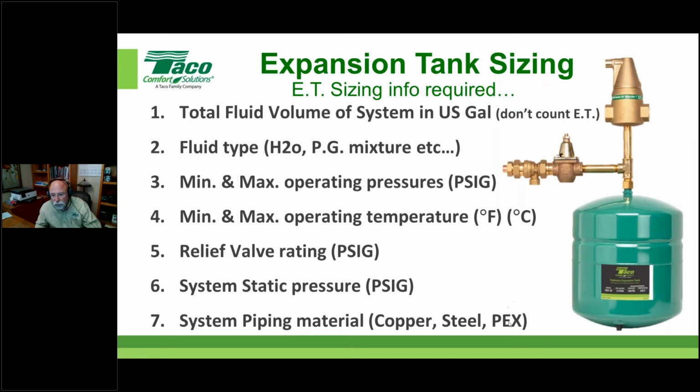I got one thrown in here, like Taco's, which if I have time, I'll show you at least an example of it. It's going to ask you whether your system is copper or steel, because the coefficients of expansion of these two materials are slightly different. Copper expands more than steel does, and it will give you the ability for a slightly smaller expansion tank. PEX, on the other hand, I know this firsthand.